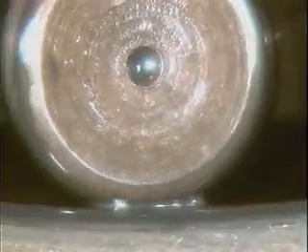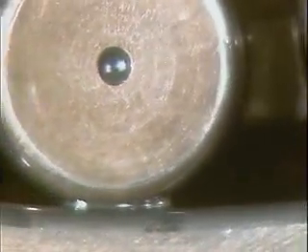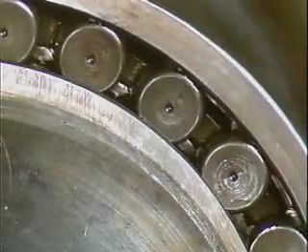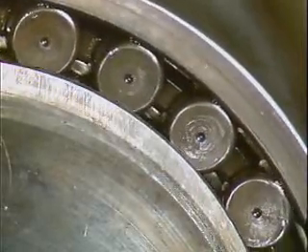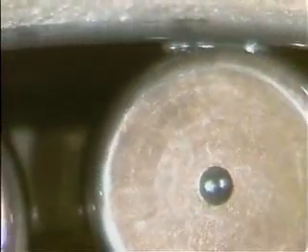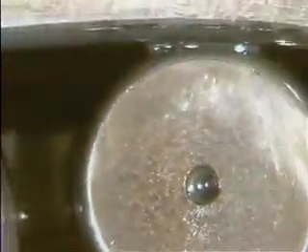One way of building a machine to minimize sliding friction is to place rolling elements between the moving surfaces. This is the principle behind rolling contact or anti-friction bearings. Although rolling contact bearings are used to reduce sliding friction, they do experience another type of friction, rolling friction. Rolling friction is the resistance to motion that occurs when one object rolls over the surface of another.